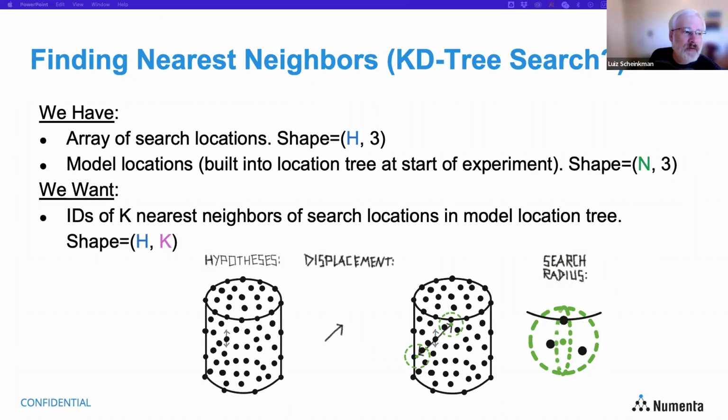Yeah, I think the only concern I have is the resolution loss, because right now we have pixels and we're going to voxels, right? So there's a volume in there. But if you're using a uniform discretization of space, which is the other thing you can do, the points are not separated by how many there are in each set, but by the space itself. If you know the max and min dimensions, like a bounding box around the space, you can just subdivide it into say 32 by 32 by 32 or 256 by 256 by 256. That gets you the voxels automatically, with a set volume for each one.